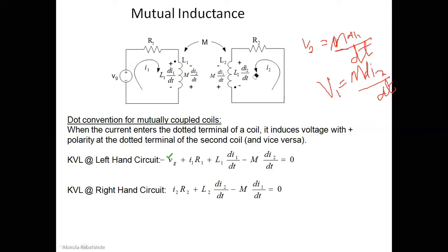All right. What you will find out here is we're starting from R2, so we are going this way. We have I2 multiplied by R2, so we have I2 R2, and then plus. Now, you will realize that we are traversing from positive to negative of the self-inductance on this L2 inductance.